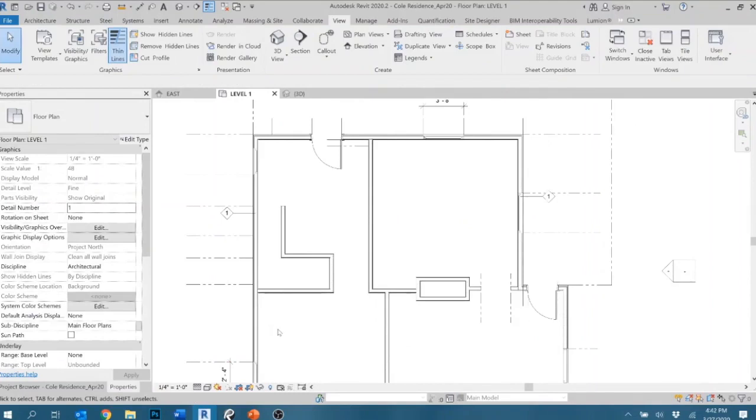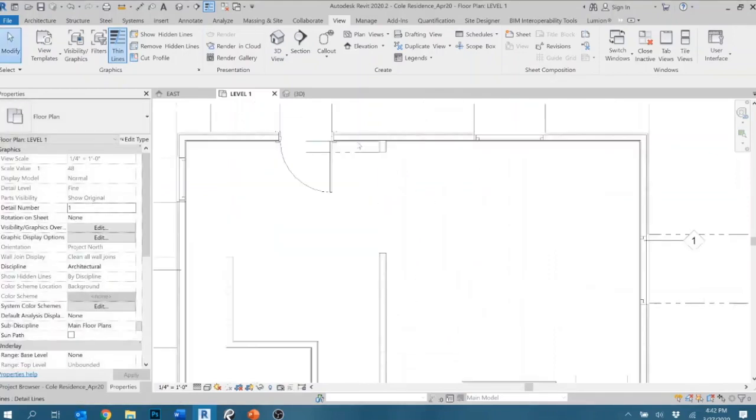Once you've drawn the interior walls, you can start to add wall openings. I have a keyboard shortcut command, WO. I'm going to start with the first string from foyer to kitchen. I offset 7 inches.